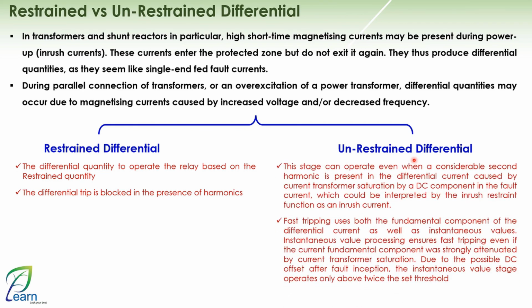This stage can operate and give results, even if an inrush condition is present. Also, the unrestrained differential will operate normally and will not be blocked.